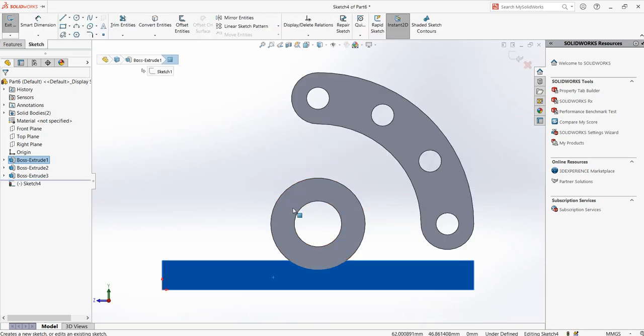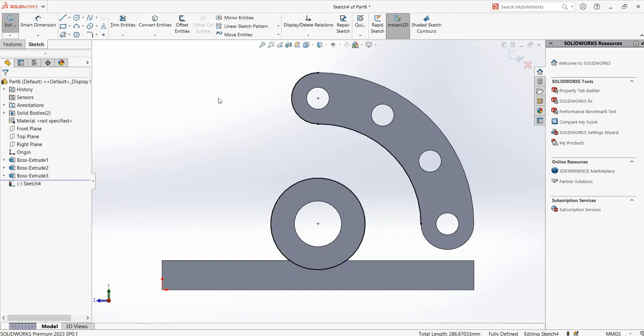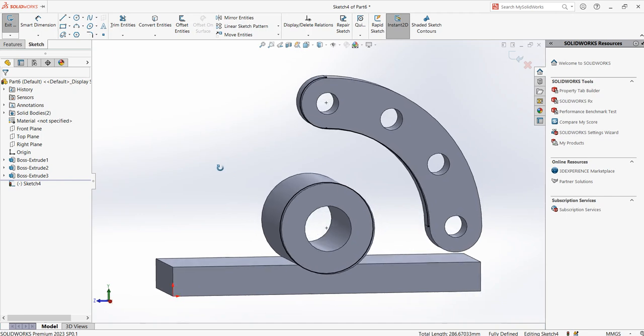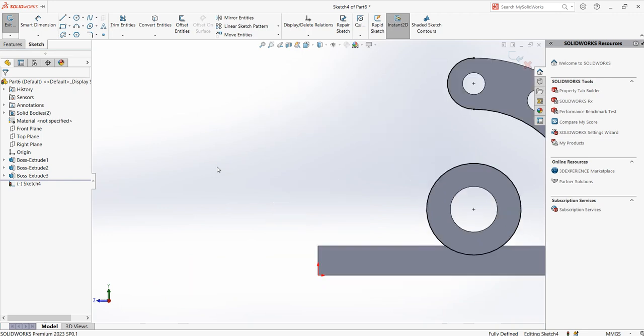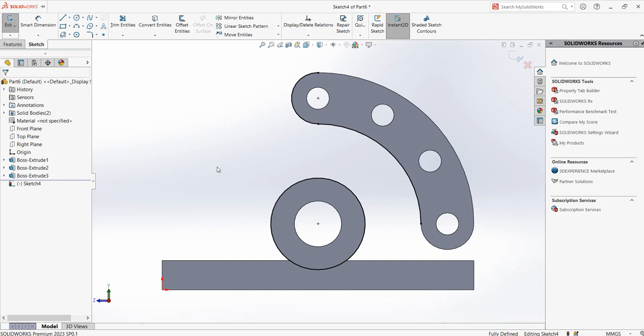Okay, now before I make a line, I need this arc here. So I can just click on this arc and this arc and this arc and say convert entity. So convert entity will just take the photograph of the outline. So you see now already a sketch is formed. Now what I can do, press Ctrl 8 to bring it inside the screen. So Ctrl 8 gives you the normal view.